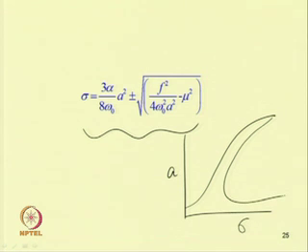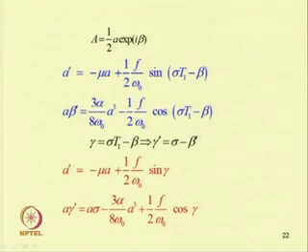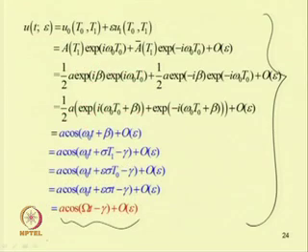one can get the response like this, where one can observe the jump up or jump down phenomena, and also one can study the stability of the system by finding the eigenvalue of these two reduced equations. By finding the Jacobian matrix and finding the eigenvalue of the Jacobian matrix, one can study the stability of the system.